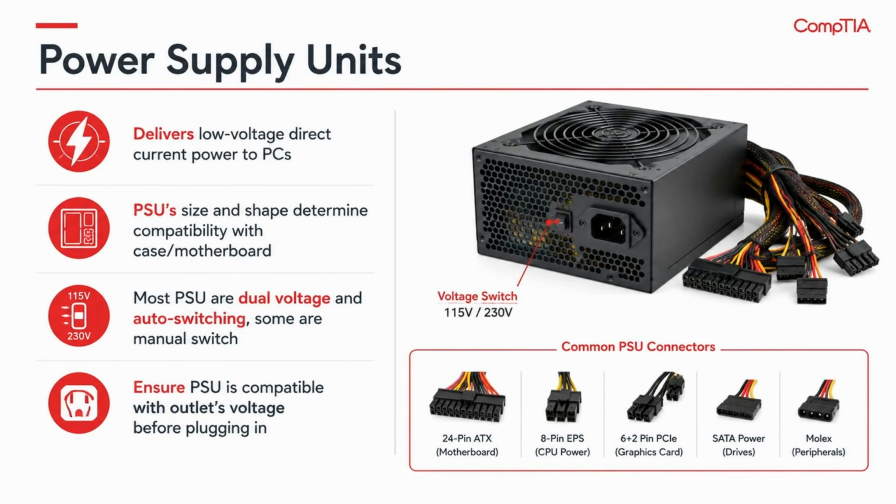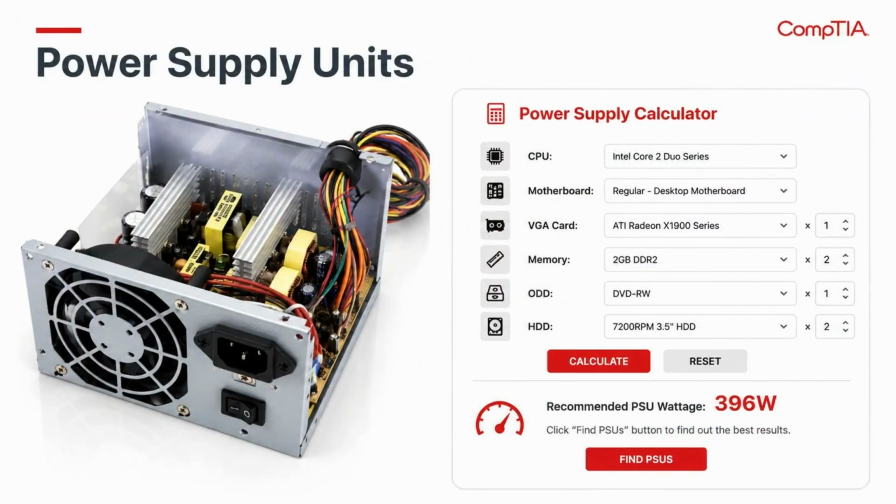While many modern power supplies are auto-switching, using a manual switch unit set to the incorrect voltage can cause permanent damage to your hardware. When planning a build, use a power supply calculator to ensure your PSU can handle the total wattage required by your components. This ensures your system remains stable under load.